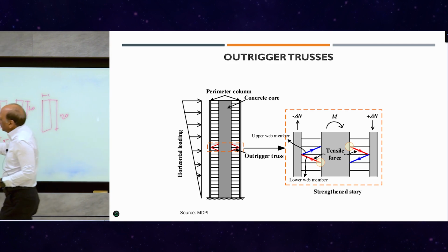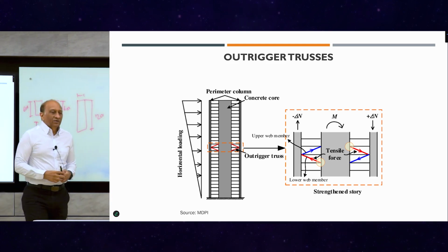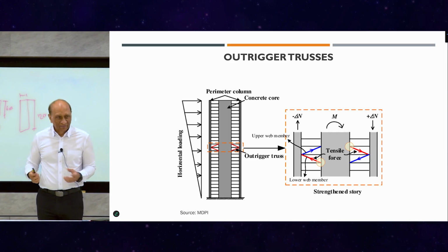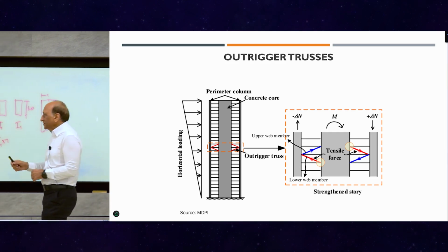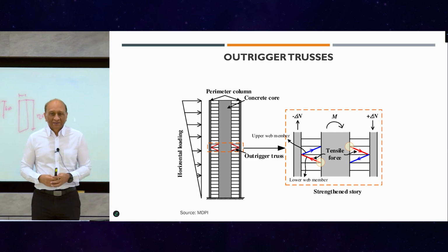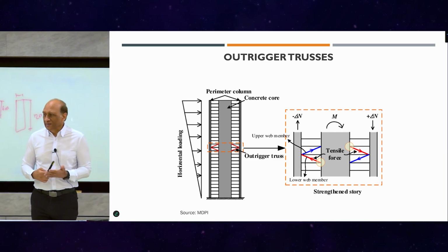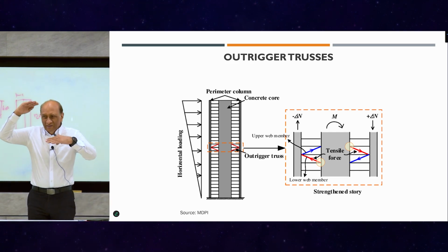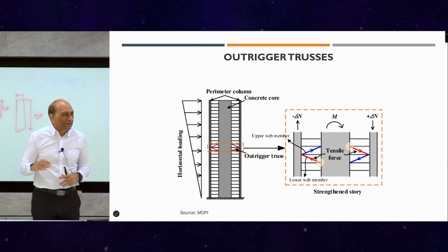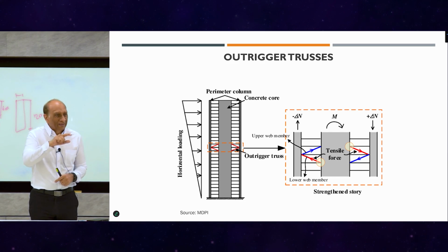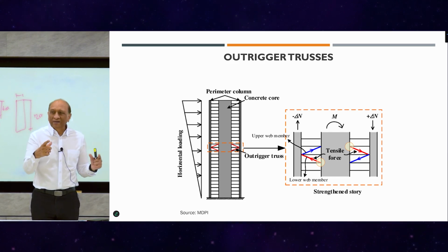And then we can replace these trusses because trusses are not good for seismic. The bracing are not good for seismic. First of all, please remember, bracings are never good for seismic response. Why do I keep making this statement that braces are never good for seismic response? Once again, I mentioned to you, for wind, braces are excellent because we keep the wind within the elastic range. So you can design the braces to be within the elastic range. Forces are controlled, so the buckling can be controlled.